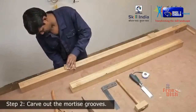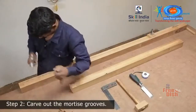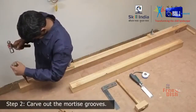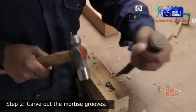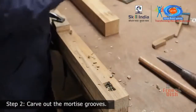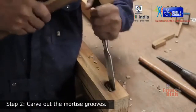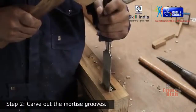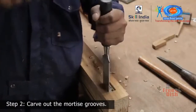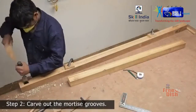Step 2. Secure the wooden piece firmly to the workbench with a G-clamp. Use a mortise chisel to start the cut in the middle. Then use a bevel edge chisel for the side cuts. Keep the combination of these two. Chisel down halfway through the mortise hole and clear out all debris from inside the mortise to leave a clean hole.